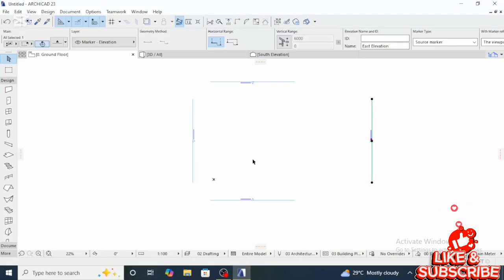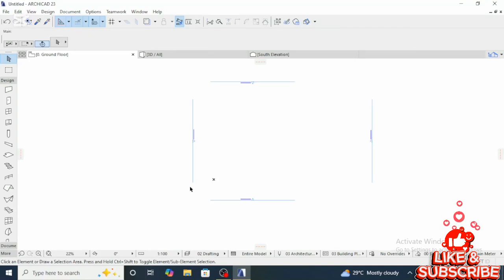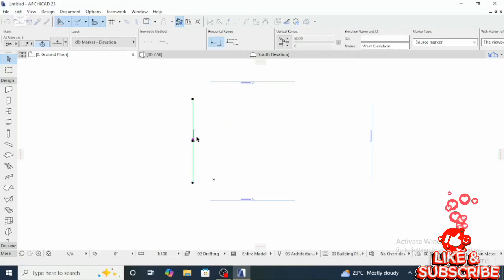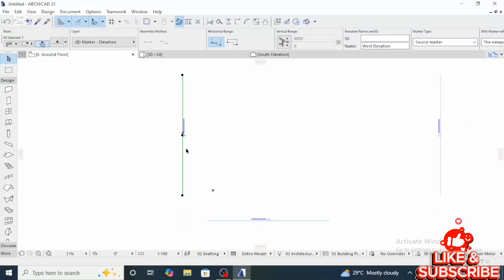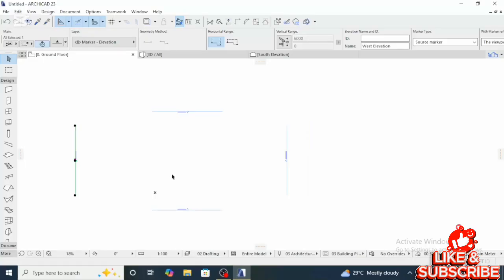You see now, you can move these north, south, east, and west poles that we have in Archicad. If we want a bigger surface to draw our drawings, I highlight this west elevation, hold down Ctrl D on my keyboard, and then move it like this, because we want a larger surface so that all our drawings can fit inside.